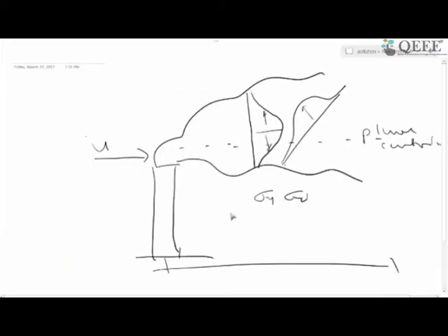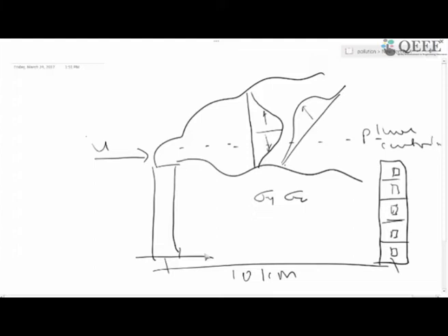In this case, suppose you would like to buy a house in an apartment, and you want to decide which floor to go for. You notice that 10 kilometers away you have a power plant, and you can use a simple dispersion equation to find out the concentrations. That will help you identify which floor to choose, depending on the concentration and wind directions.